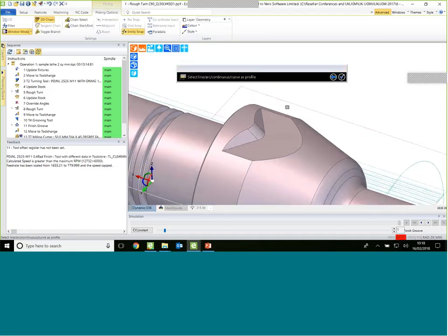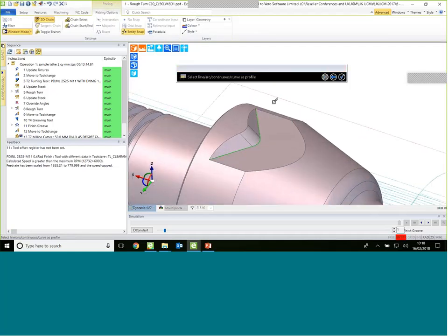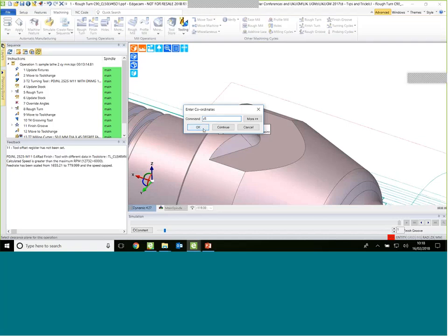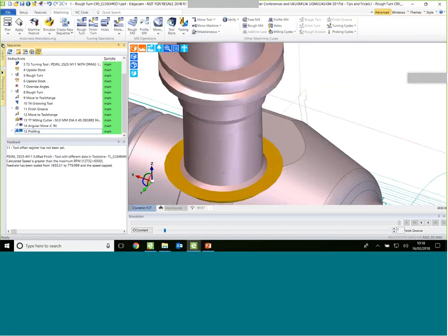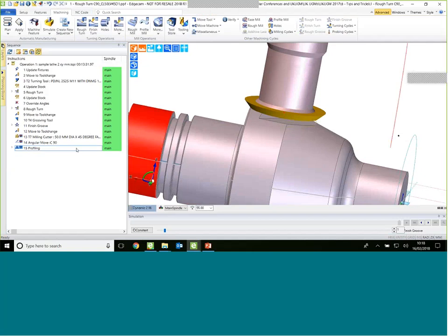So here's the usual questions. What are you machining? So I'm just going to, as you can see here, chain the edges. There's no need to have geometry in those areas. Where's the level for this command? I can pick this area here. Where's the clearance? I can say with reference to the same spot, remain 5 millimeters above. And then finally, where's the point for the depth? It's there.